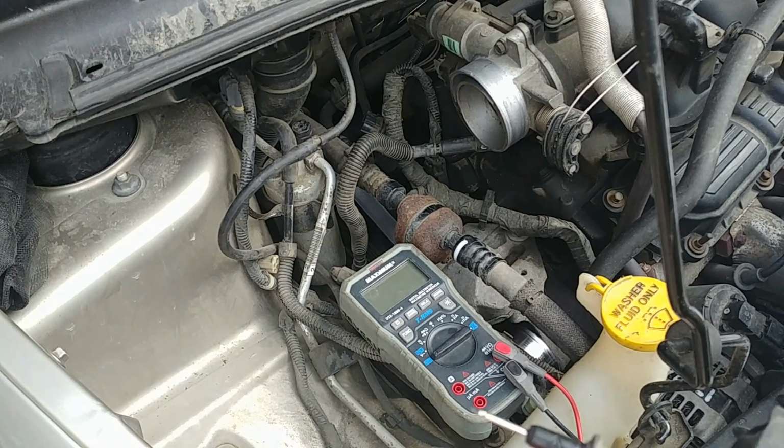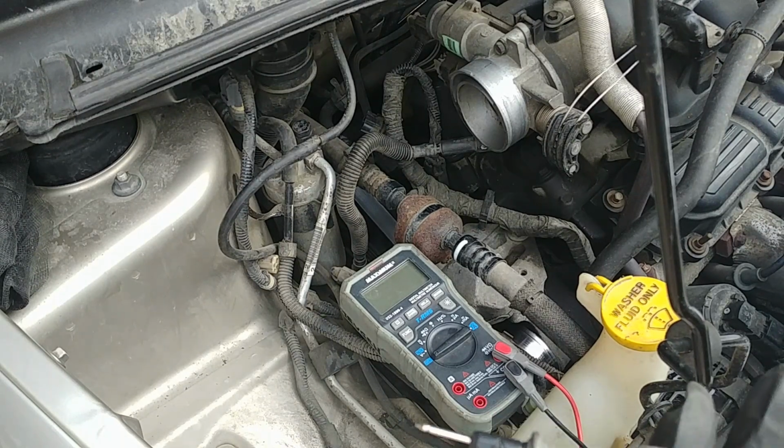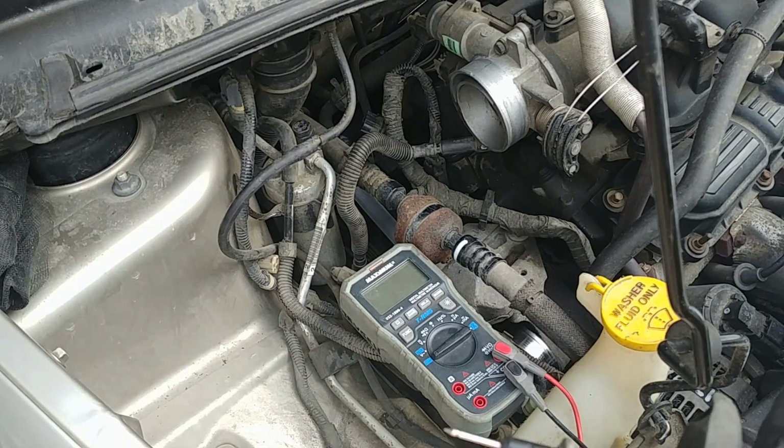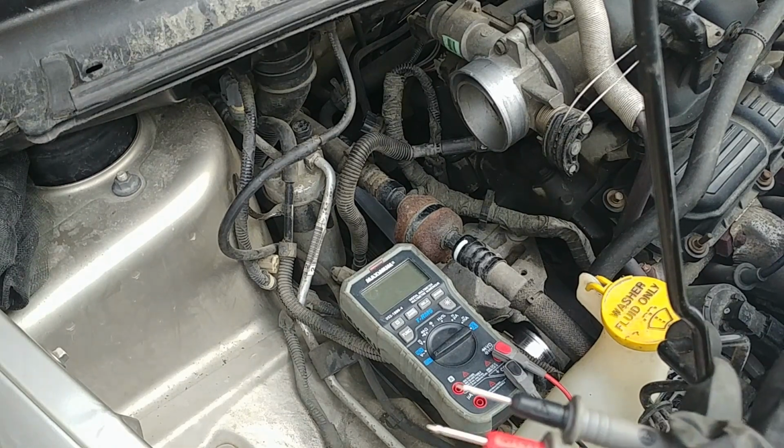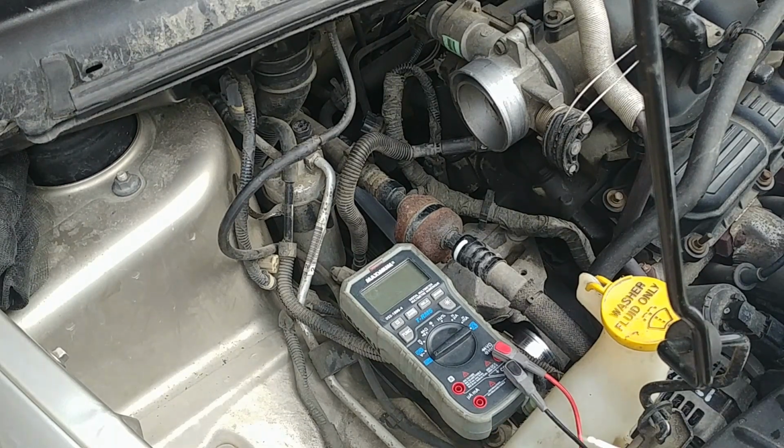It might be your wiring or connector broken or fried after excessive heat on the sensor side. That can normally happen. Also it can be a relay issue or no power supply to the sensor, or your PCM computer unit can be faulty.